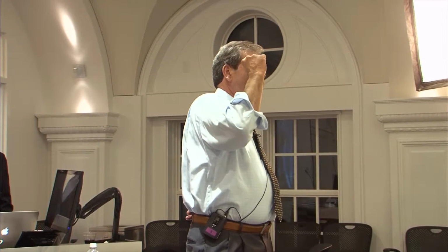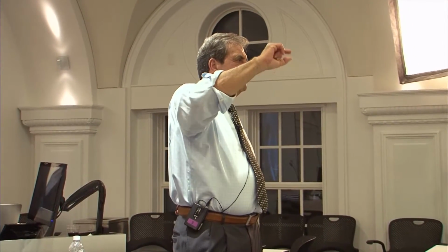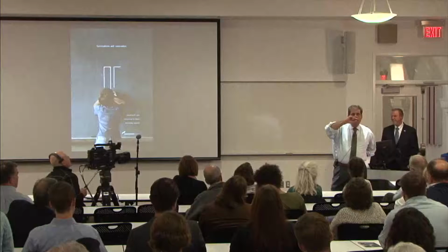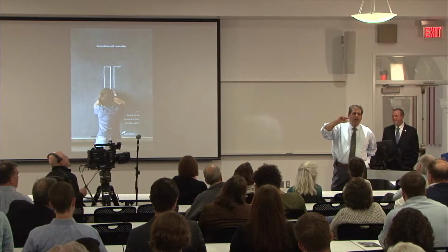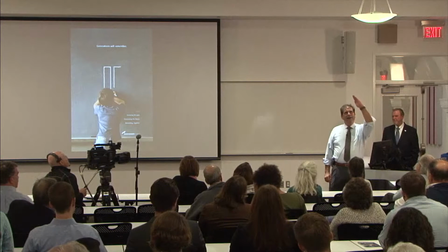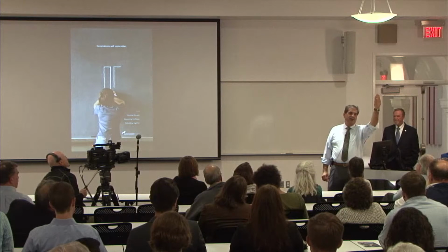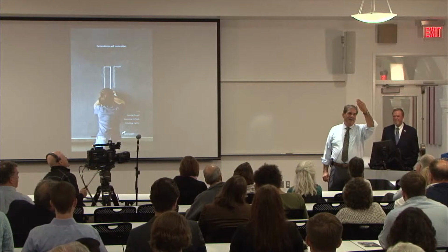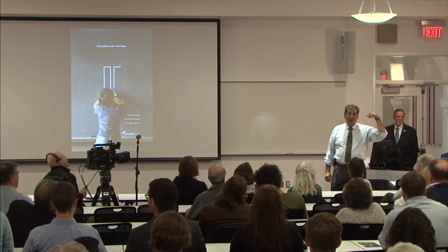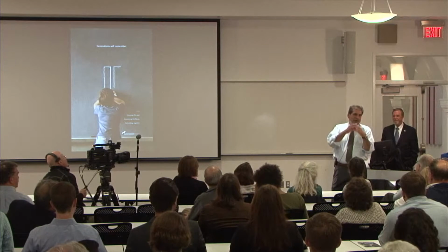And what was interesting is, it's such a sensitive structure to its own erection that we were doing studies, as we were sequencing the erection, of how the overall structure moves if we put this component in. If we want it to be in its final configuration in this place, where does it have to start to end up there? Because you have to understand, everything there is welded. We used erection bolts to put the pieces together, but then they welded for a long, long time.